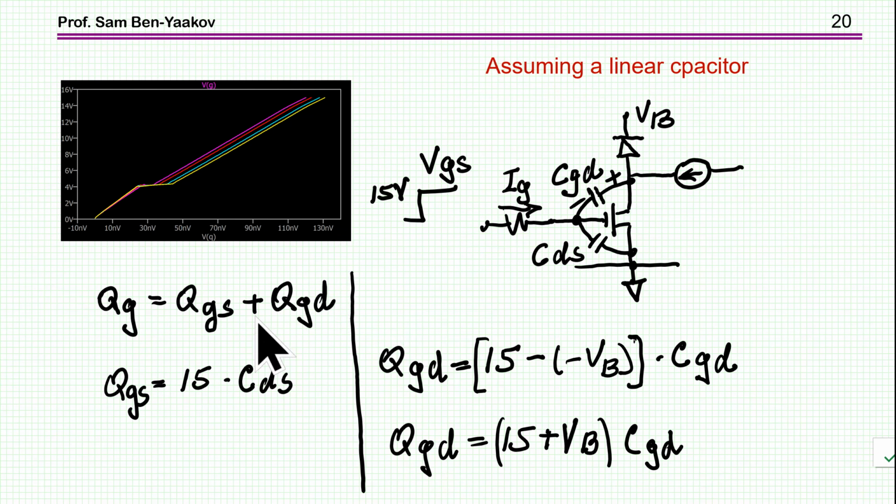So now let's see what is the reason for this plateau and what is called Miller effect, but I'm going to explain it without actually resorting to the idea of the Miller effect. Now, the Miller effect talks about an impedance that is between input and output. And there is an amplifier, there is a gain, and then you see this impedance to be larger.